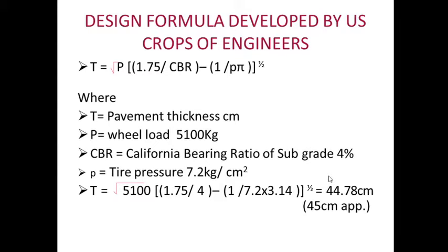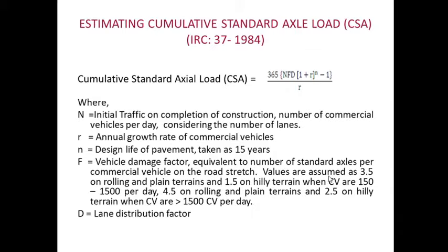That 45 centimeters includes the thickness of the subbase as GSB, granular subbase, the thickness of the base course as water bound macadam or wet mix macadam, and the surface course as bituminous concrete or bituminous macadam. Then we can discuss the CBR method. In the CBR method, we estimate the cumulative standard axle load, that is repeated load.